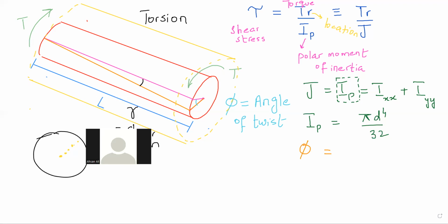Let's talk about one simple thing. I have this pen, circular. Increase the length, increase the length, make it 10 times. I stand on one corner, I hold it. So now it's like around 6-7 meters. You stand on the other corner and you just twist a little bit, right? Repeat the experiment. Now we reduce that 5-6 meter length to this length. Again, you hold it from here and I twist. We apply the same torque, right? All of us know how much it will twist. The 6 meter one will definitely twist more, and this little pen, for the same torque, will twist less.